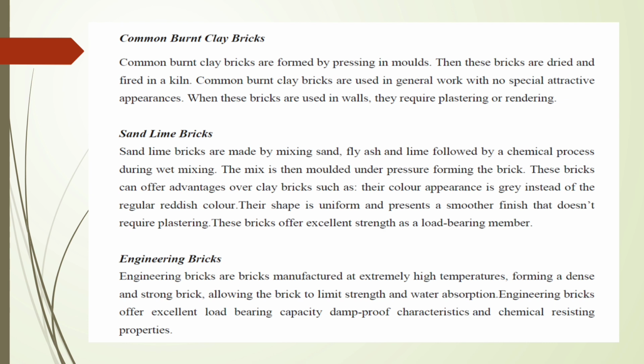These bricks can offer advantages over clay bricks, such as their color appearance is grey instead of the regular reddish color. Their shape is uniform and present a smoother finish that does not require plastering. These bricks offer excellent strength as a load bearing member.